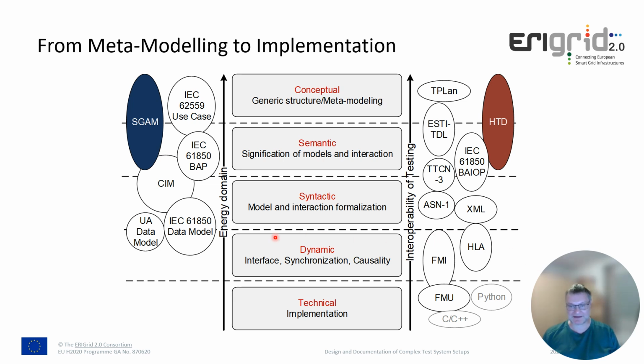For the interaction between different tools, we typically have different interfacing and synchronization approaches, like the functional mockup interface and the high-level architecture. For the syntactic description, for the modeling and interaction, we typically use more formalized approaches like XML. We have also semantic models, and for the description of the interactions that you can see here, IEC, business application interoperability profile, and some others.